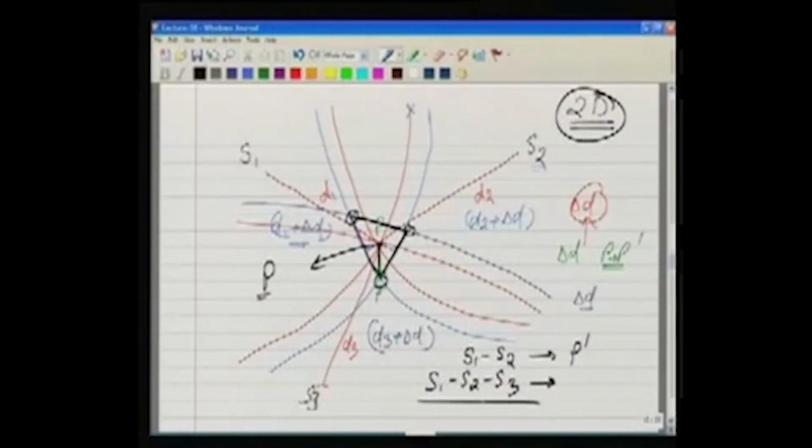The meaning is, in the case of the GPS, even if there is error in the receiver, its effect can be eliminated by observing distances to 4 satellites, because in the 2D example, we saw that 3 satellites can solve the problem. So, in the case of the 3D problem, we will have to have 4 satellites.